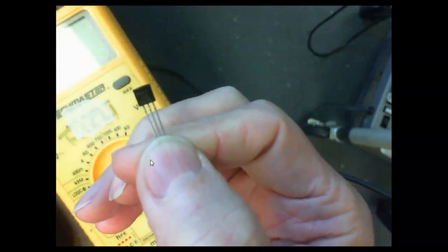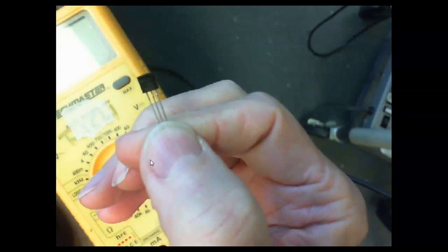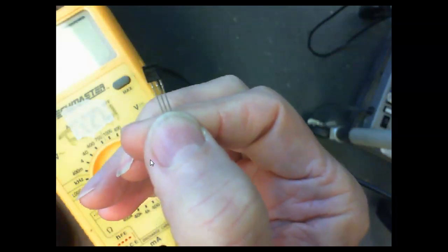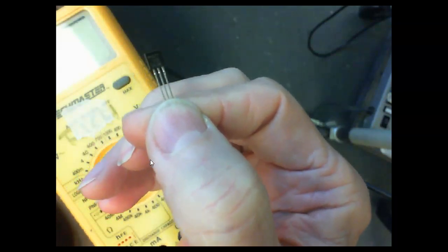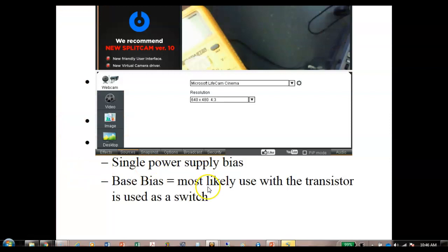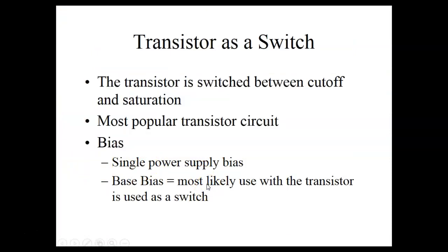This could be an SCR, or a triac, or a voltage regulator, or a transistor. It could be a bipolar transistor or a field effect transistor. If it was an FET, I wouldn't be handling it like this, by the way, because those are susceptible to static discharge. Just because you see one of these cases doesn't mean it's a transistor. It could be a lot of things. That's when you would make sure you look up the part number.